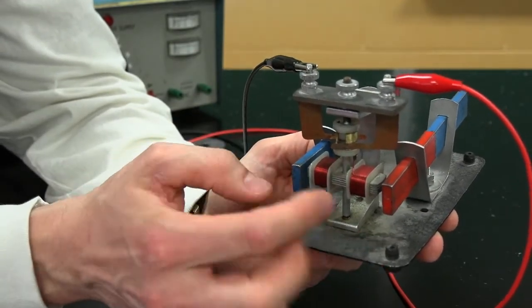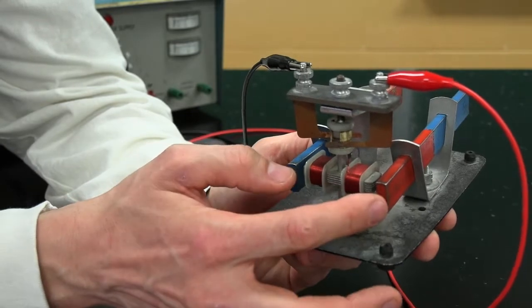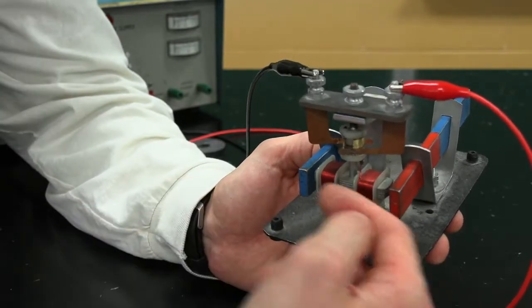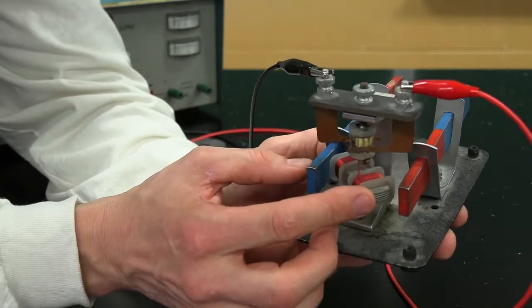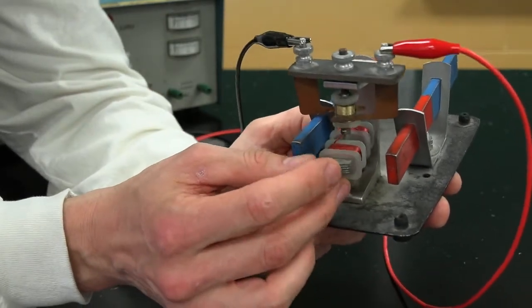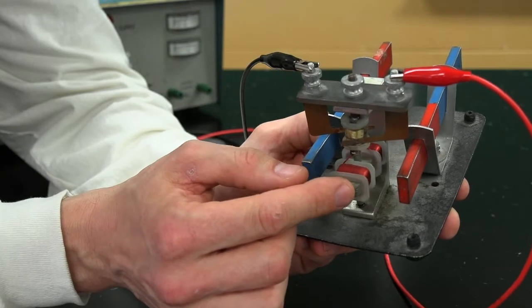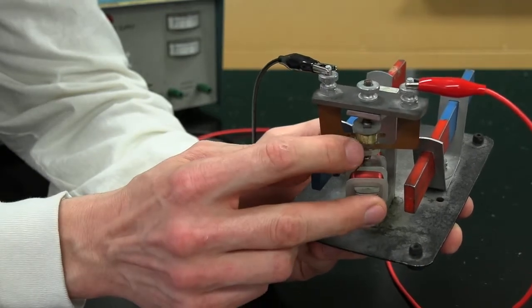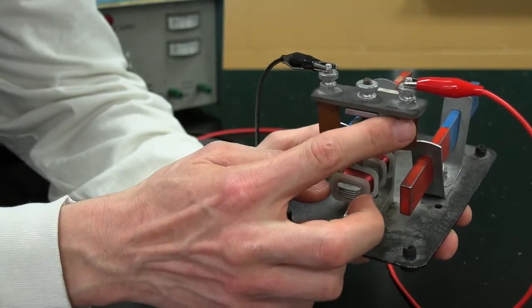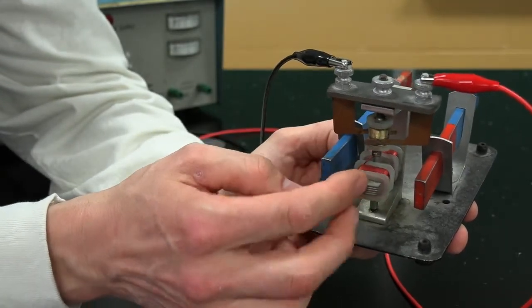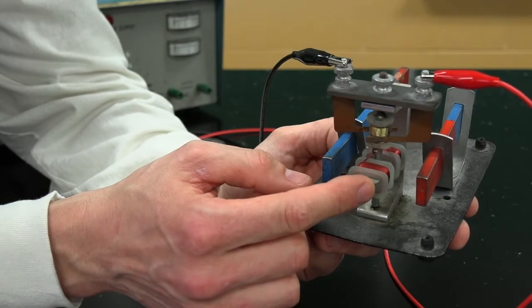So I have my magnetic field here. This is the south end of the magnet. This is the north end. The magnetic field goes like this, and I got a couple coils. Now if I turn this and hold this like this, you can see that this coil touched by my finger is right now connected this side to the positive wire through this brush, goes up here, and so I've connected this part on my finger to positive.